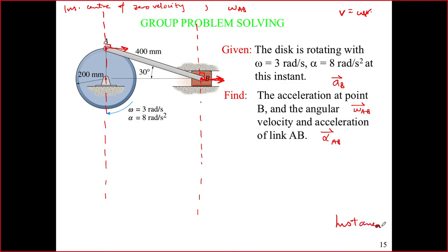So overall, sure, at the next instant this rigid body will go back into general motion, but right now the velocities of the two are parallel to each other, and the instantaneous center lies at infinity. That means r_B/C or r_A/C, whichever you want to say, they both lie at infinity, such that now it comes to this: if v is equal to omega r, and r is infinity, what is omega? Zero, absolutely right. Well done, Munj.